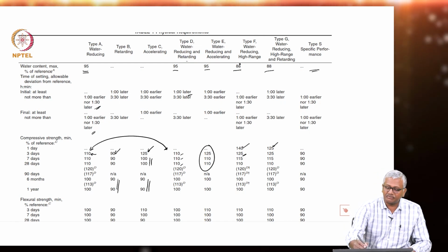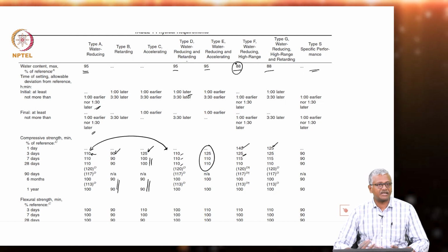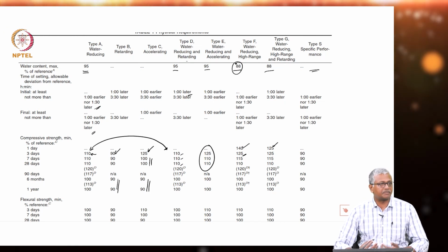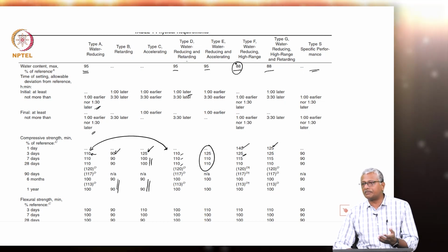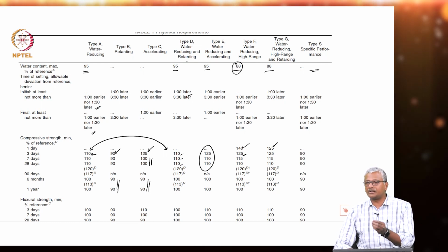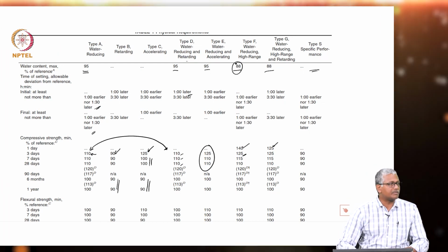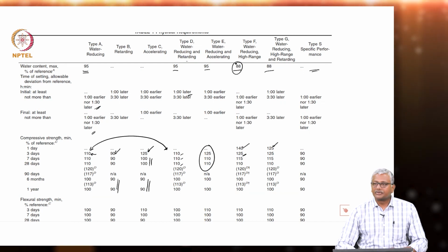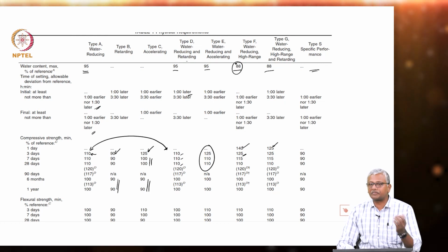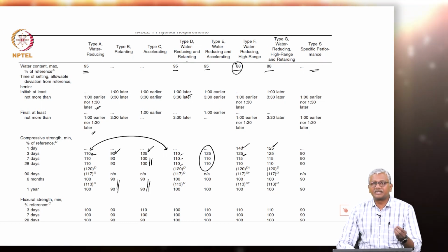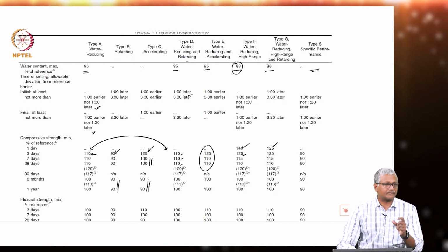Okay, all this has to be achieved with 12% minimum water reduction. So, you can also design your concrete mix with 80% of the water content of the reference, that means 20% water reduction. Okay. So, all that will be determined by the recommended dosage of the admixture to be used to provide that level of water reduction, and that is provided by the manufacturer. Okay. So, when the laboratory certifies these products as type A or type F, they are certifying it based on the range of dosages recommended by the manufacturer.